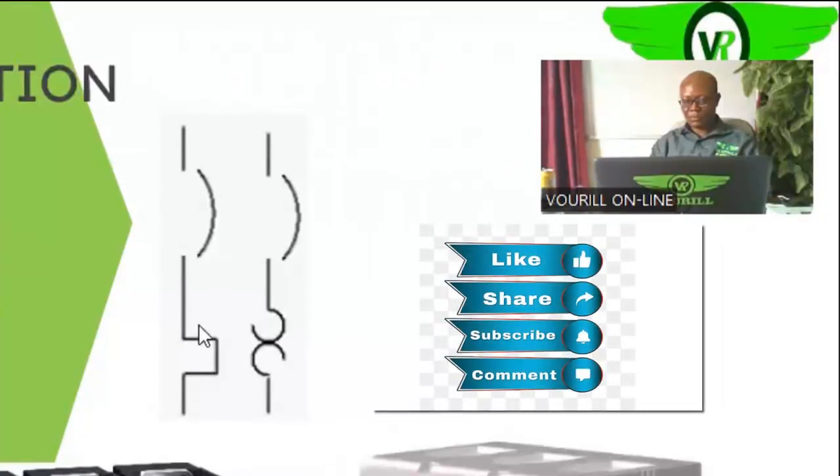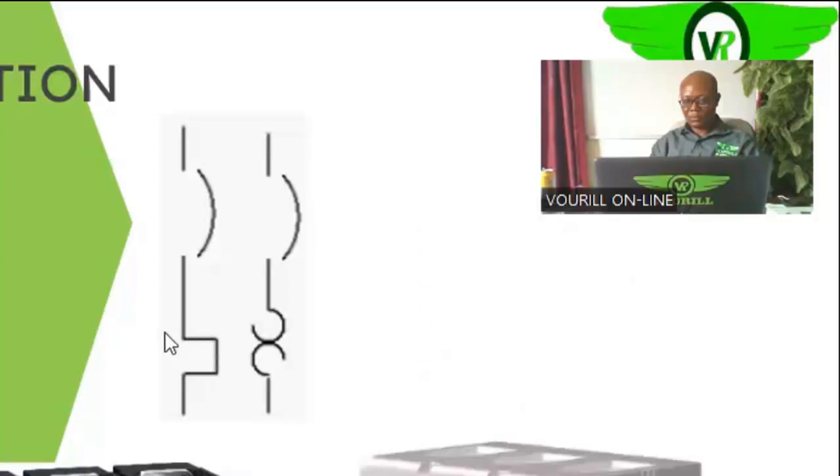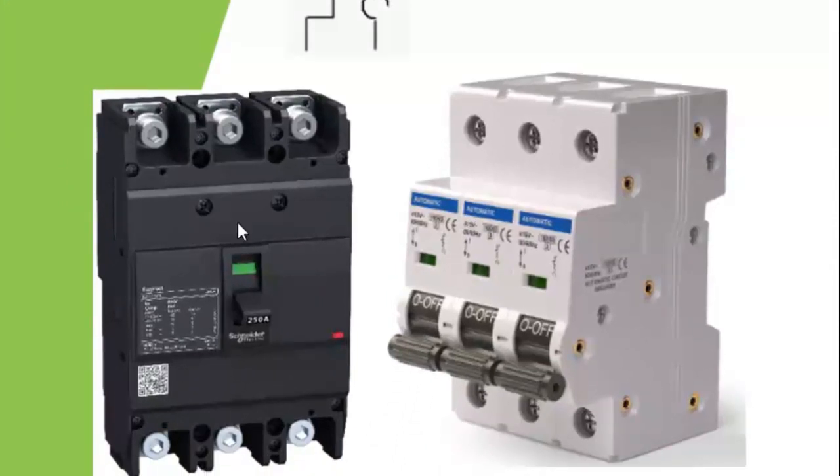So this is the symbol of thermally operated circuit breakers. You can see the thermal element represented by what you are seeing on your screen now, and this is the circuit breaker. It shows clearly that what you are looking at is a thermal circuit breaker. Here also is how it is represented. This is the NEMA representation of the thermal element of the circuit breaker, and this is the IEC representation. Here we have some examples of the circuit breaker, which I believe you are familiar with, that use thermal and magnetic elements to control the tripping of the circuit breakers in the event of a fault. We'll come to see all of those later.